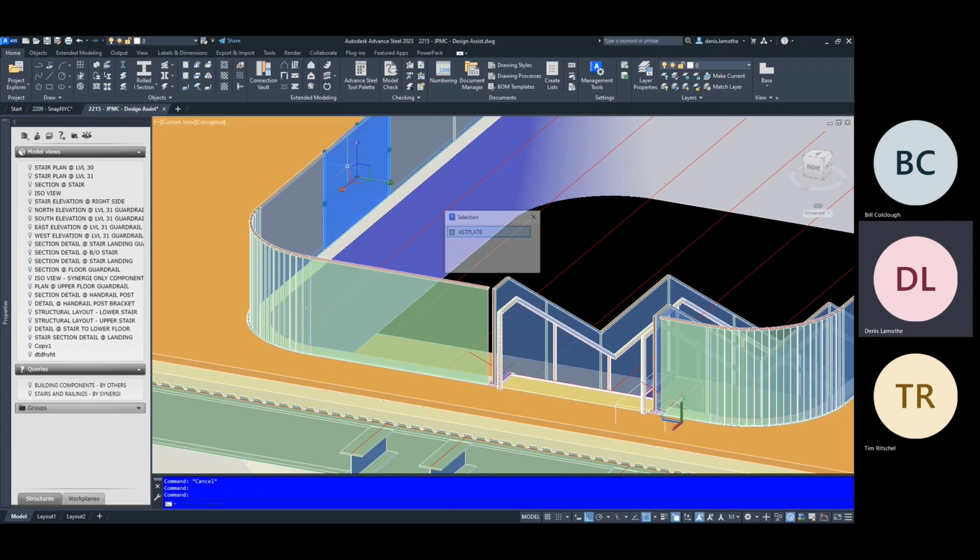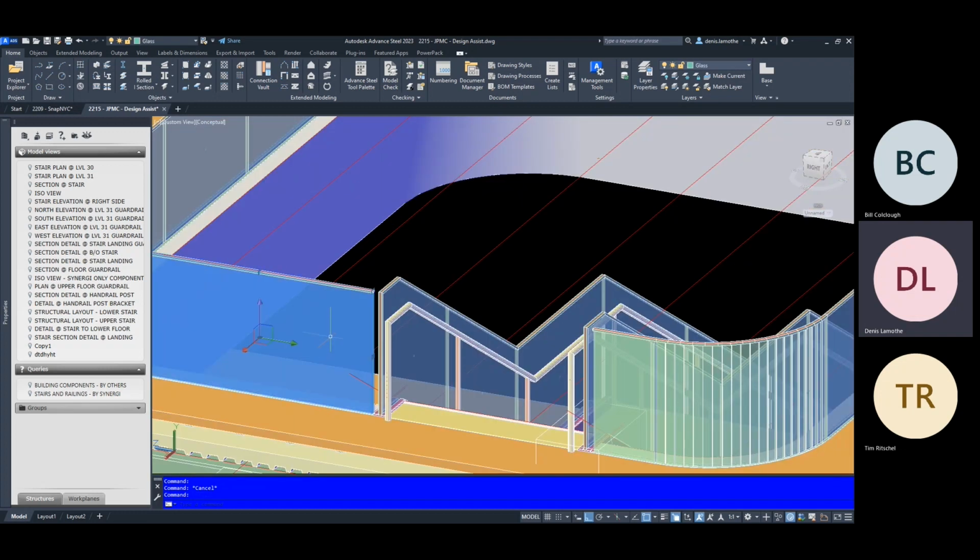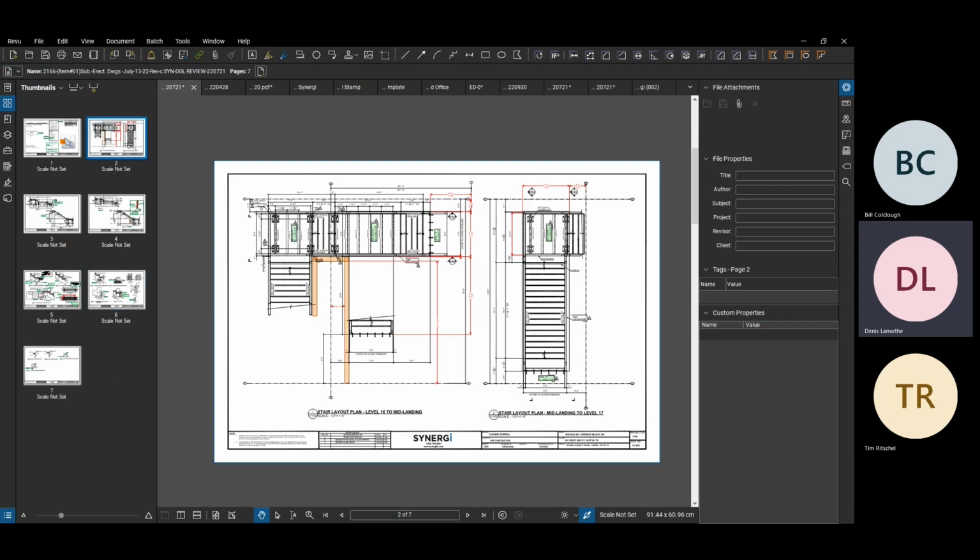Generally it's not an issue between glass joints, but it could be a problem where we are tying our glass panels to, say, a wall, or sometimes where we have a curtain wall, right? To the outside, there's a curtain wall. I don't know if you're familiar with curtain walls, but there are mullions and glass panels, and these mullions can get in the way of the glass panels getting close to the actual glass unit of the exterior wall. Those mullions can get large at times and may force the edge to be more than 4 inches from the glass. I'm going to see if I can sketch it out just so it makes a little more sense what I'm talking about.